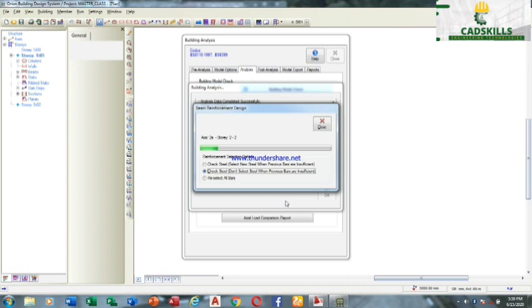Now, where we have done all these changes of the arrangement, remember, if there is no proper transfer of load, it will not analyze. If there is no good connection of beam to column, it will not analyze. It means that your load cannot be transferred very well. So for your analysis to run completely successfully means there is proper transfer of load from up to foundation. Please take note of it.